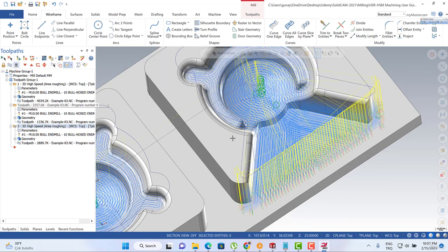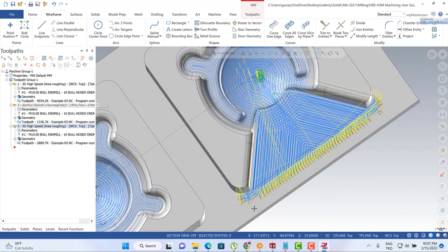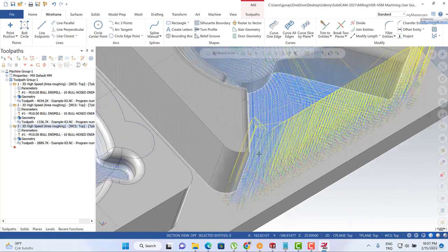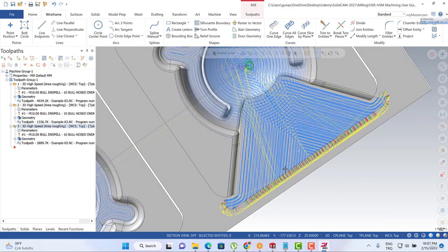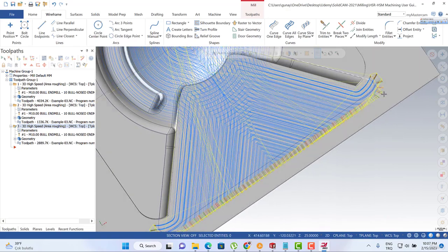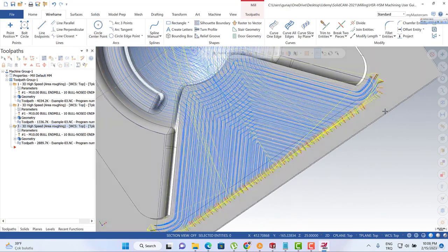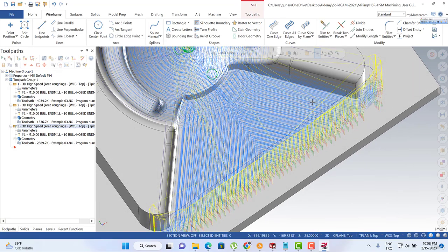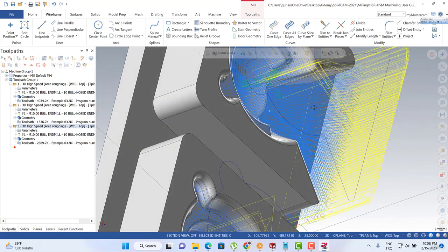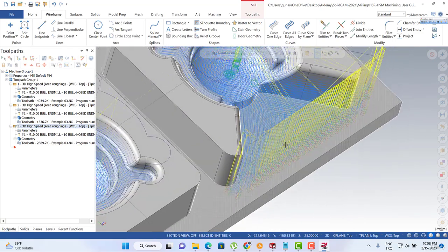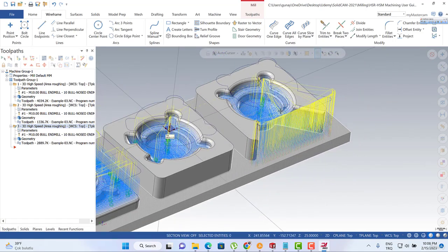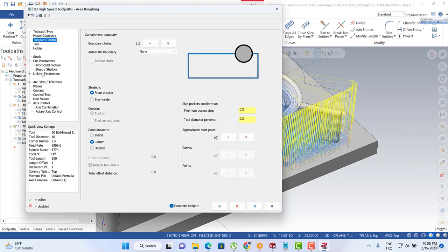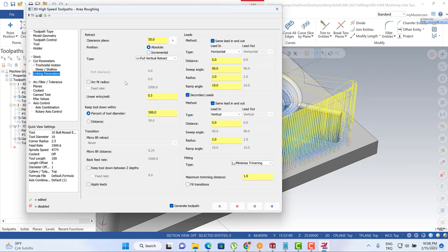Let me check my toolpath. Yes, we can also see here that we prefer to use the outside, so that's why. And my boundary, moving to the outside of the boundary, is the entry process. So that part is quite important. Okay, we can also see the rapid movement here. Maybe we can also change that by focusing on linking parameters.